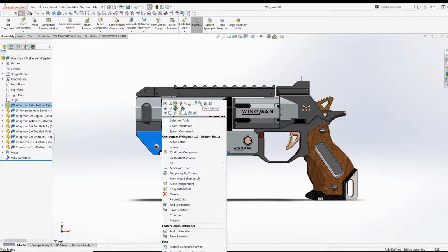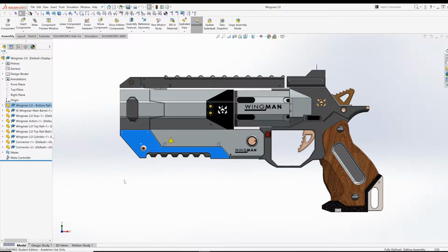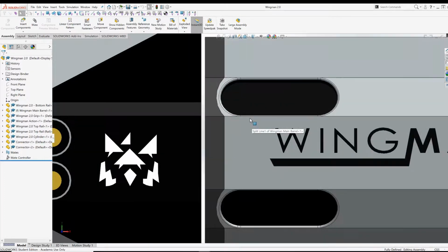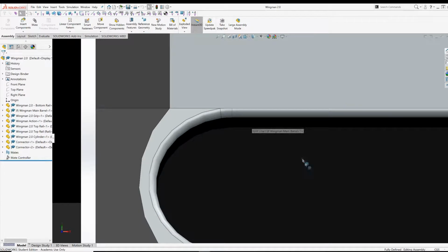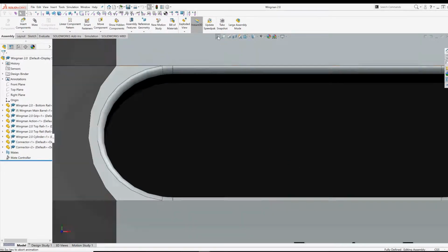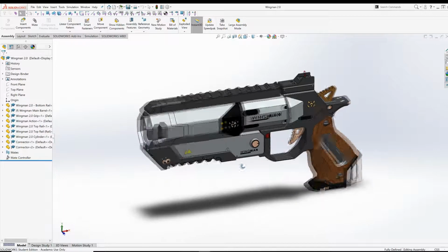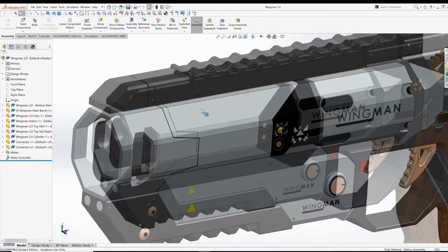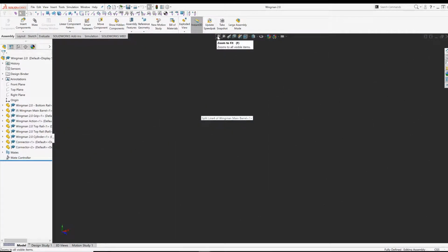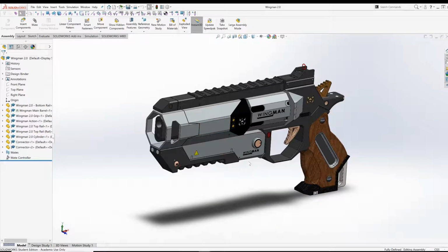So if you want to view when you're welding things in some sheet metal, you can use that as well. Come down here, I usually like to have these six all pointed out. You have the top level annotations, sketch dimensions. You can control the visibility of sketches, but you can also do that by just clicking on a sketch and then hitting the I button to show it, and that'll show the sketch wherever you want to go. But I usually keep them off, especially when viewing a big assembly like this.